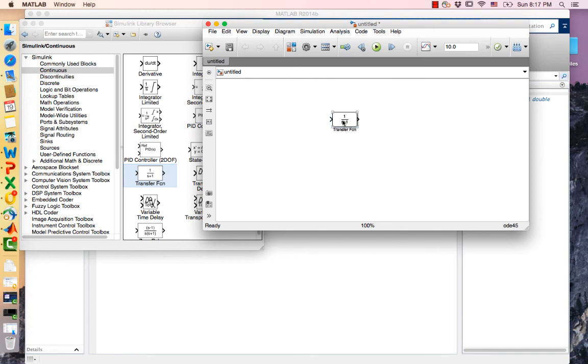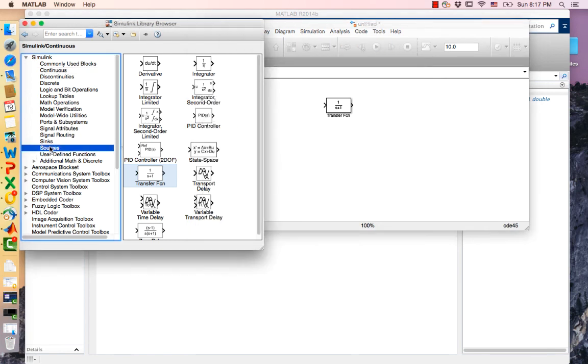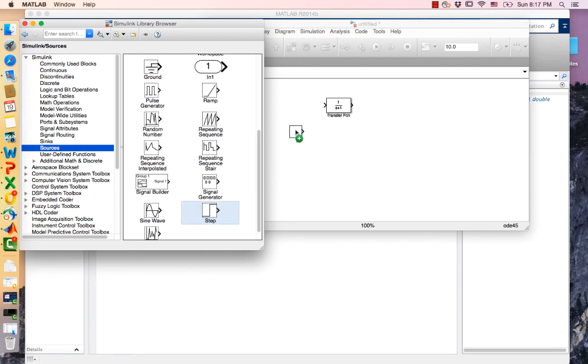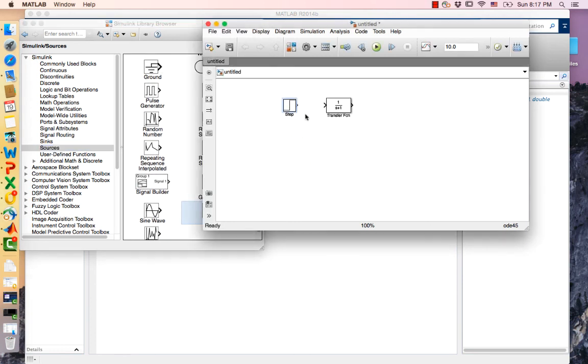Okay, this is the basic one they generated for us. I want to start with this one, then we'll show how we can change it based on this default one. So we say we want to display a signal. The first thing, of course, we want is a source. So the source is, let's say, a step function, because we want to monitor the transition response.